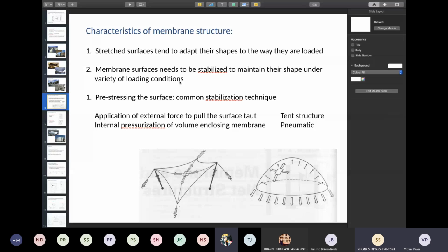In portals also, you have seen that if it's a cantilever portal, then you have worried about the uplift, because it's a cantilever load. But in tensile structures, it is not just a cantilever, all the points, you are going to worry about the anchorage more than the support.